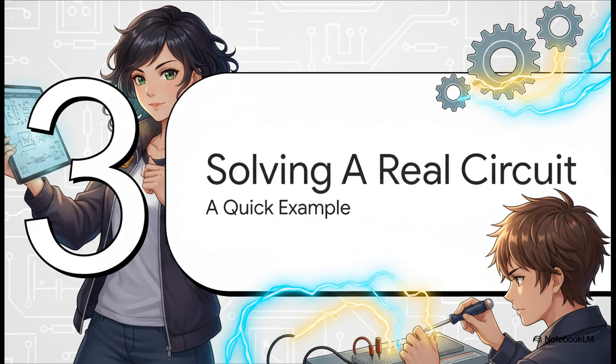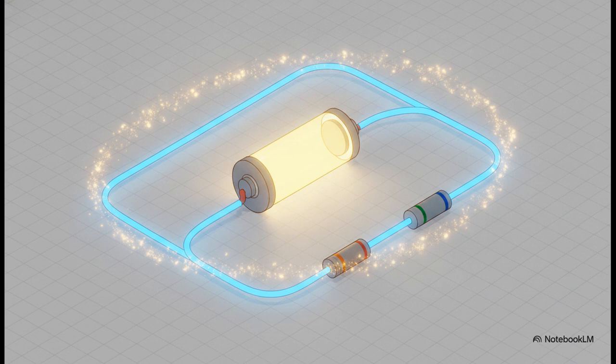Let's do a quick example. Time to put you in the driver's seat. Imagine a circuit powered by a standard 12-volt battery. We connect that battery end to end with a 4-ohm resistor and a 2-ohm resistor. Because it's a single loop, we know right off the bat it's a series circuit. Our goal here? To calculate the exact current flowing out of that battery.